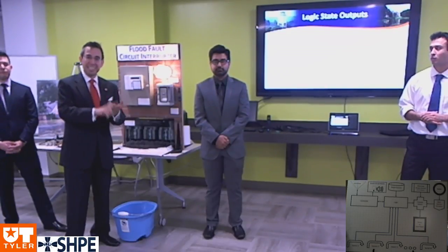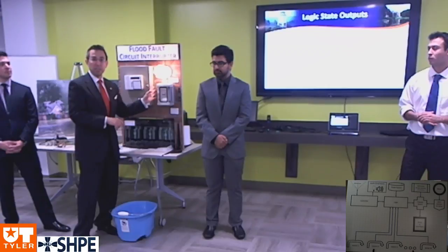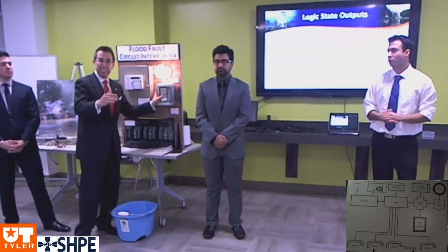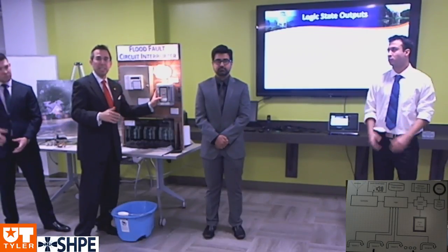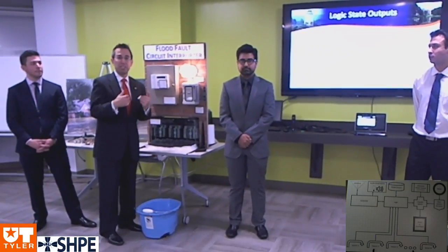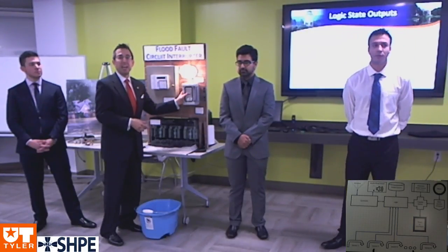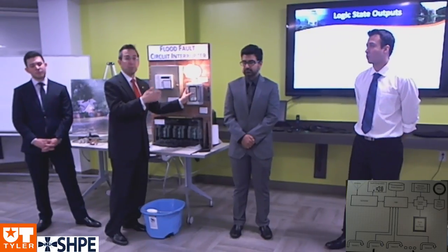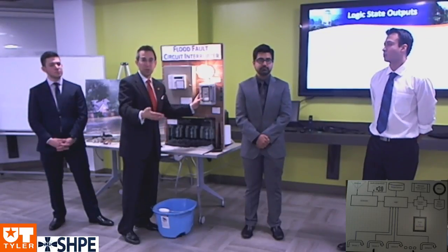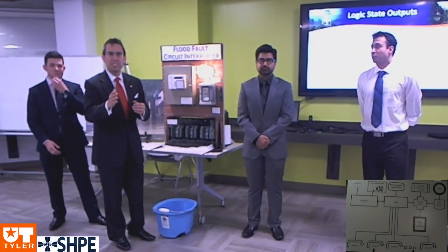Absolutely. NFPA, NEC, and UL listing were all things we consulted. Our system, as it stands today in the prototype mode, is only UL listed, which basically means that this breaker cannot replace an existing breaker that you'd have for a branch circuit in the home. Again, the primary limiting factor for us today in that design is the cost of what's available off the shelf. This is essentially a part that Cyrus was able to source for us through ABB, but there's no reason why a version that is both UL listed and NEC compliant as a primary circuit breaker couldn't be sourced. It's simply not readily available for us to prototype. Did that answer your question? You answered my question, yeah.